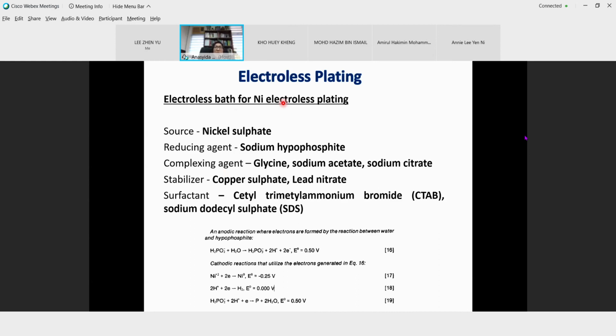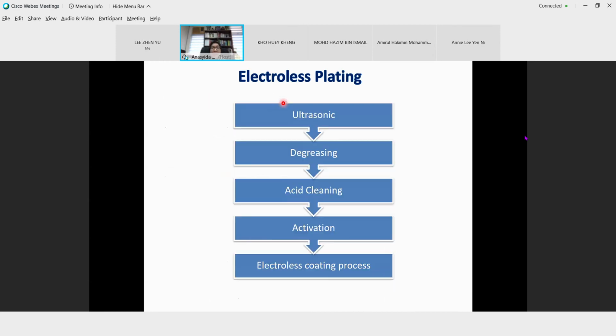They also can use electroless plating for cutting tools, but it has to have other material embedded that can give you strength. For example, people are using composite, so they embed ceramic particles, turning the electroless coating into a composite electroless coating. They embed other particles to add hardness and wear resistance. So you can add ceramic particles during the process of electroless plating.